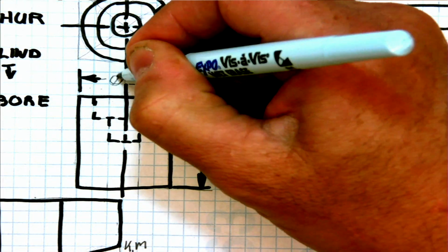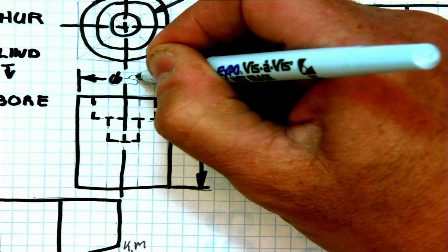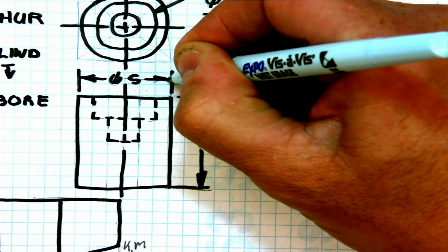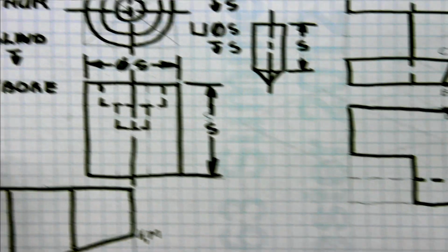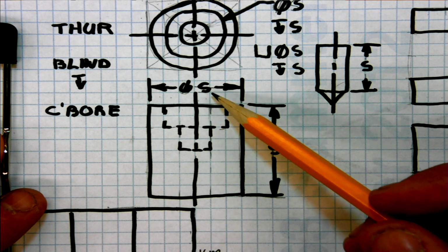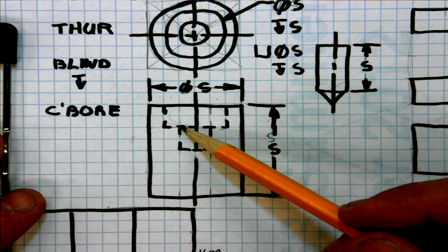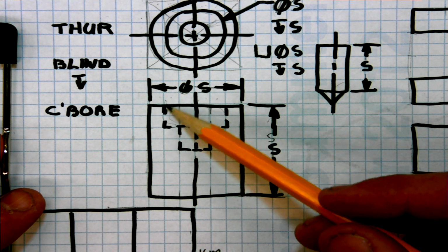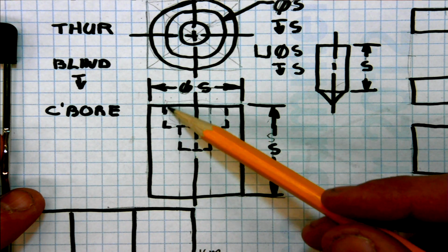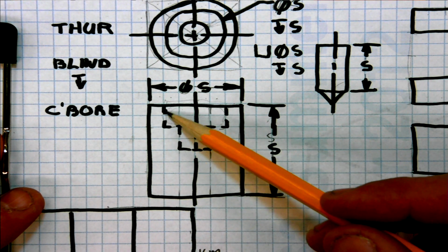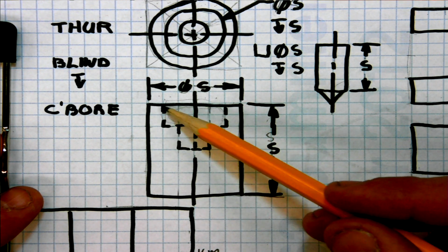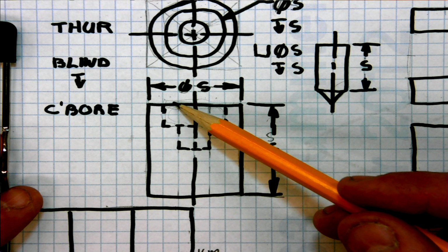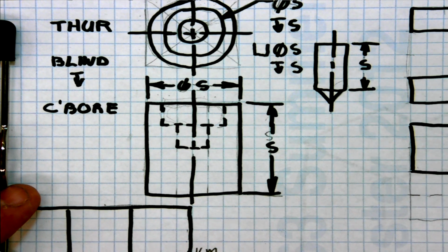This makes life simpler. So you have arrows popping in your head. Okay, one more here, the countersunk hole. Well, again, I'm going to skip back to here. The reason why you do counterbore holes is you want to drop something in this hole that will not stick out above the surface. So let's say you put a fastener here, a cap screw. You would drop that in here, and you want that thing to be below the surface of the object or flush with the surface of the object so something could clear it. So that's why you use a counterbore hole.